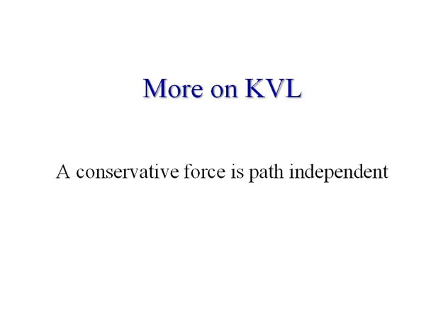In this video, we'll take another look at KVL, Kirchhoff's voltage law. We've applied it according to the loop rule, which says that the change in energy throughout the system must equal zero. That means any energy increase must be equal to the energy decrease. We applied that in terms of energy per unit charge, which gave us the sum of the voltage increases around a closed loop must equal the sum of the voltage decreases around the closed loop.